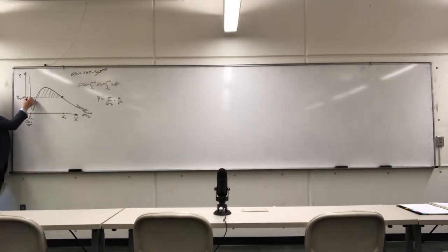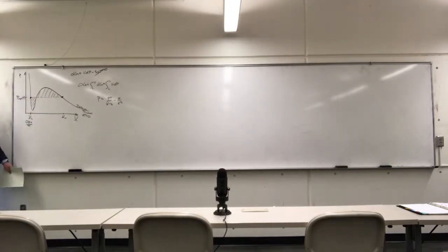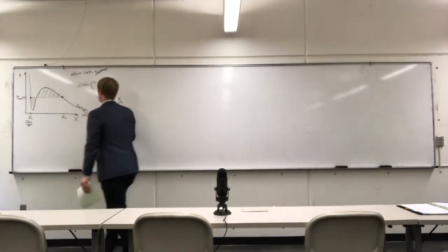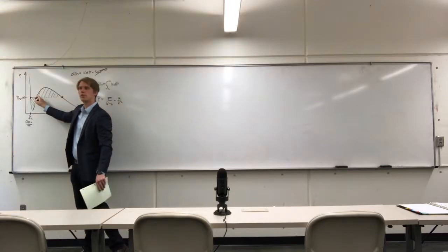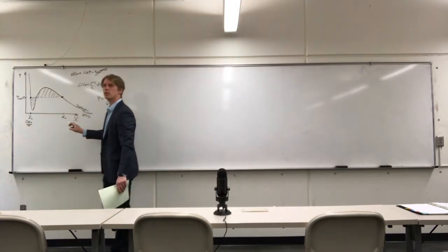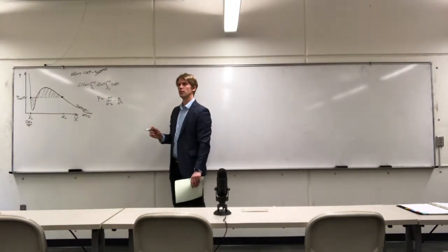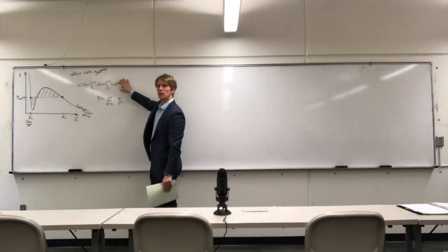If you guess a pressure, we may or may not know that it's the right pressure for the vapor pressure. These roots already involve the solution to a cubic equation of state. So we have to solve this expression here. There's going to be 3 roots, 1, 2, 3. The middle root is not going to be a thermodynamically stable fluid, so we neglect it. The smaller of the 2 roots corresponds to the liquid. The higher of the 2 corresponds to the vapor specific volume. Then once you've completed that step, you have to go ahead and actually integrate this expression.